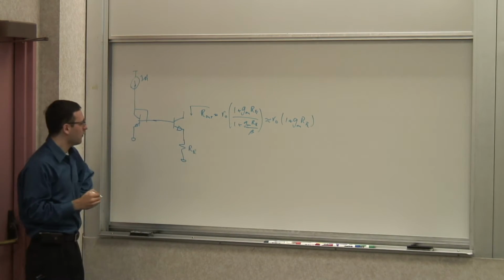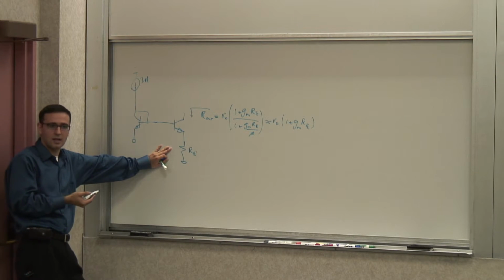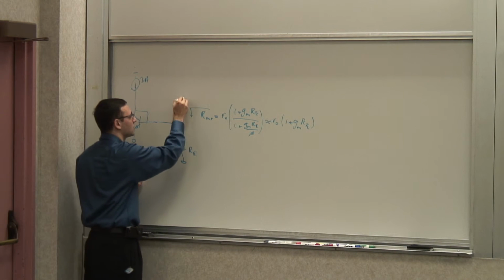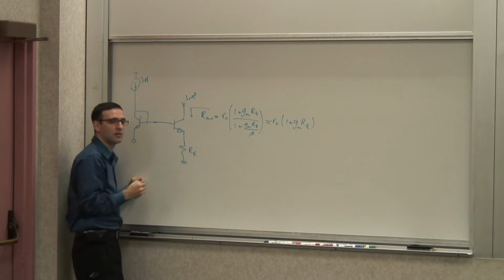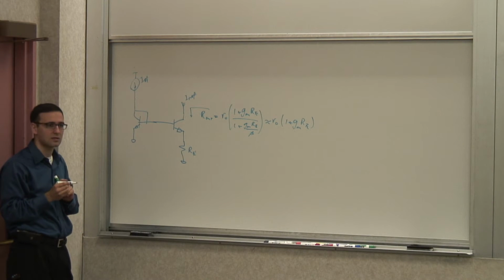Now, if you do just this, we know that the current is going to be very small. That would be the wrong current source. Now, how can we keep exactly the same current? Let's say I wanted to replicate the IREF. I just needed to get exactly IREF here. And I wanted to get it at the higher output impedance. How do I do that?